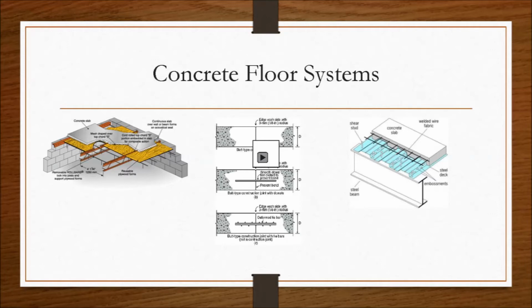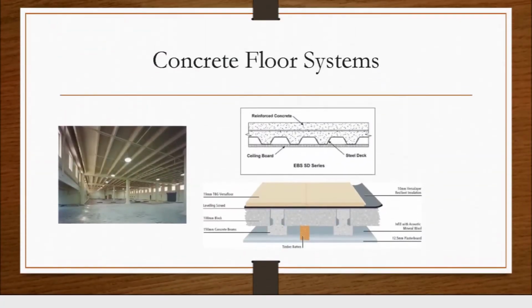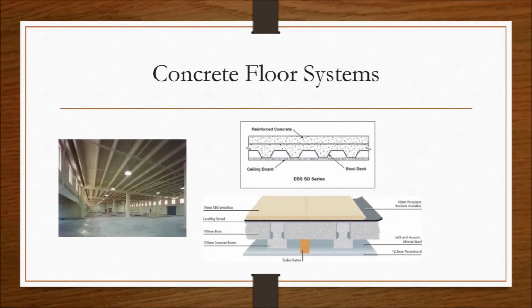The subflooring material must be smooth and level and suitable for installation of the floor's finished material. Construction joints are found between adjoining pours of concrete. Expansion joints between two parts of a structure allow for thermal expansion and contraction. Control joints are continuous grooves or separation inserted in concrete or masonry structures.